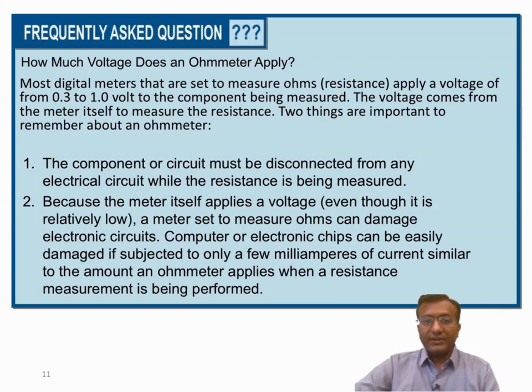Now coming on to the next concepts. There are certain cautions that you should consider while measuring the resistance in the circuit. Remember, an ohm meter applies a small voltage to measure resistance, so the component must be isolated. For example, if you are testing a sensor in a car computer system, disconnect it from the circuit. Measuring in circuit can damage the computer's sensitive components due to the ohm meter's applied voltage.